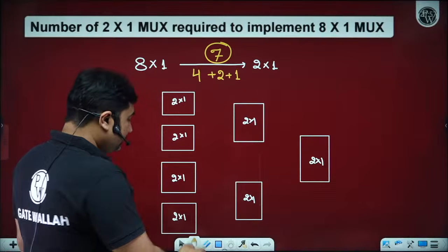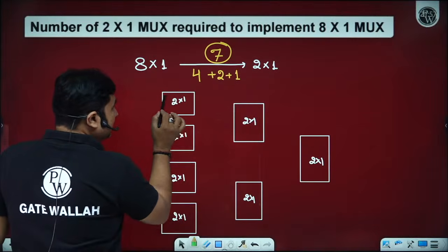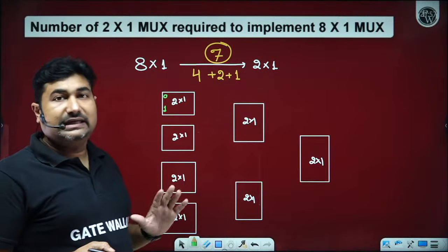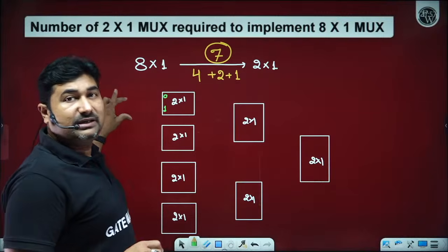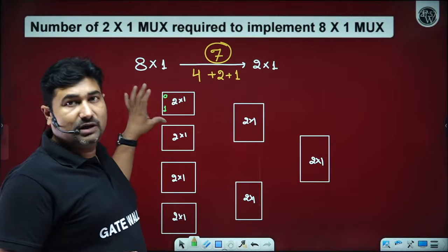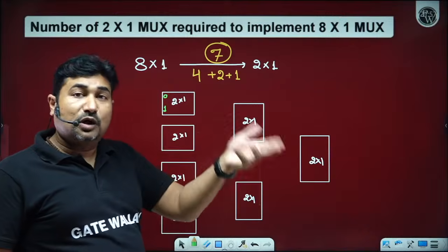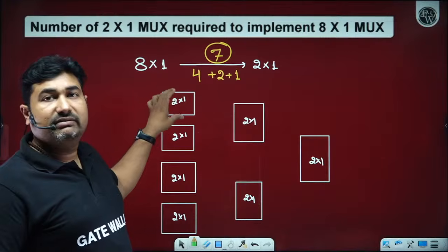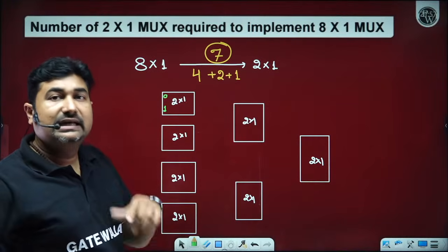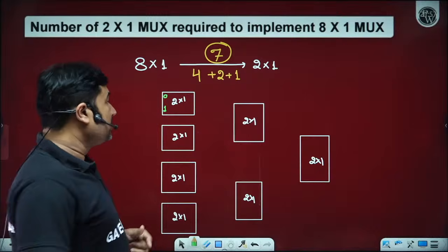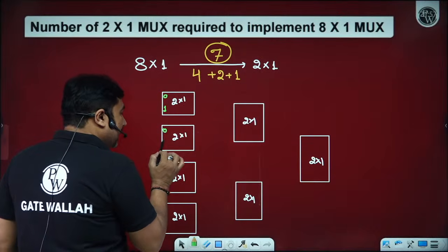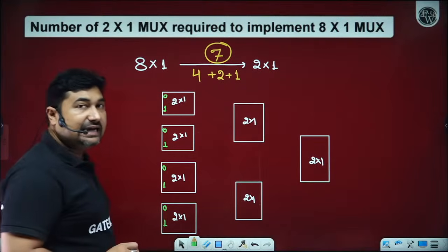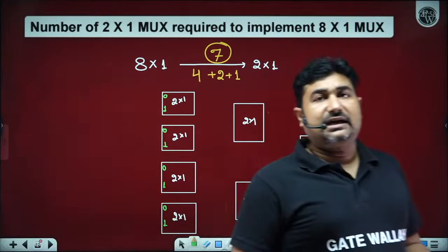Standard representation in general: if 0 and 1 are represented inside the multiplexer, then that is indicating I0, I1. Outside the multiplexer box, any logic level represented is the true logic level applied at the input. Inside the multiplexer, the labels in the box usually describe the input pins. So we have I0 pin, I1 pin, I0 pin, I1 pin, and so on. Instead of writing I0 and I1, sometimes it is directly represented as 0, 1.